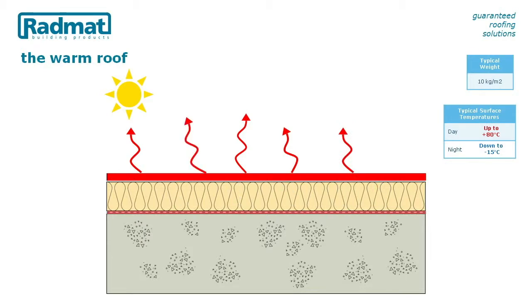This UV degradation by the sun creates high surface temperatures, causing the material to expand and then contract when temperatures drop. Over time, this puts strain on the waterproofing material and can cause irregularities in the surfaces and cracking. Ultimately, these factors will cause the failure of the roofing system, typically anywhere between 10 and 40 years into the future, depending on the waterproofing material.